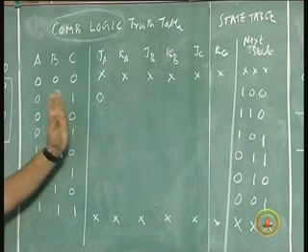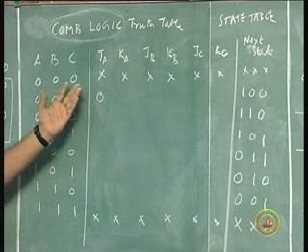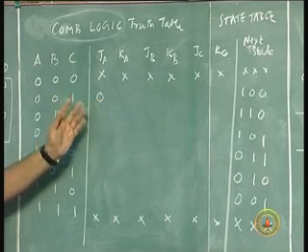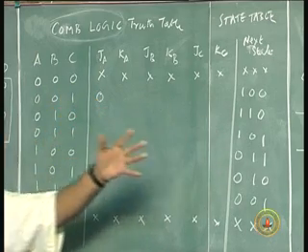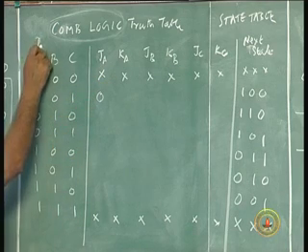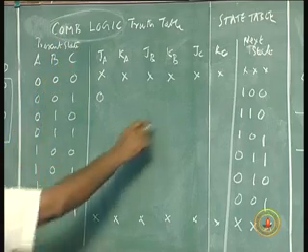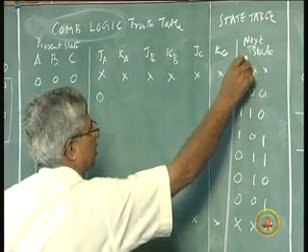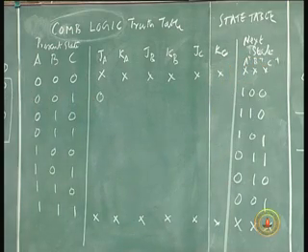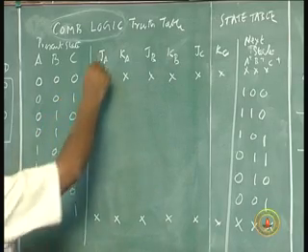Actually, I should have put it here next to this, to make it convenient. Since I use the same table from the D flip flop, I just change the inputs from DA, DB, DC to JA, JB, JC, KA, KB, KC. I am putting it here. Actually, it will be nice to write the present state values of the variables, and the next state values of the variables, this is really A plus, B plus, C plus, and then the corresponding flip flop inputs.